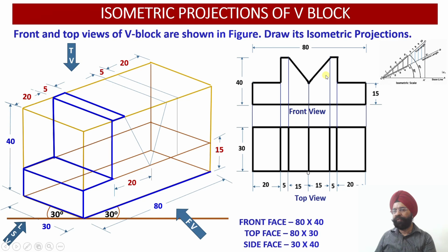That is, this is one piece. Had we got one solid line over here, it would mean that there is some change in cross section over here. Since this is a single surface, we have not drawn a solid line between these 2 points. Now having obtained the base, this side, that is the right side of this block, will be developed.